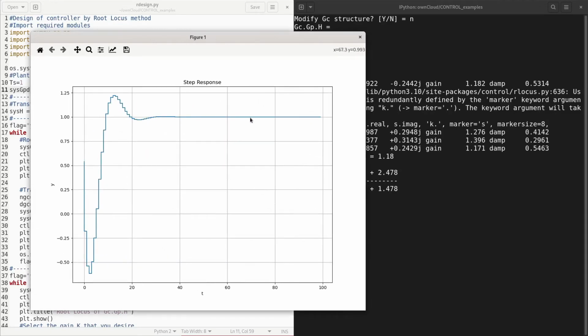The steady state part, you see that it has reached the stable state, error 0, because you have one pole in the loop gain. In the loop gain transfer function, you have one pole at z equal to 1. And then you have those transients. So at 0, you see from 0, it immediately goes down below negative and then starts pulling up and then tries to track the reference.